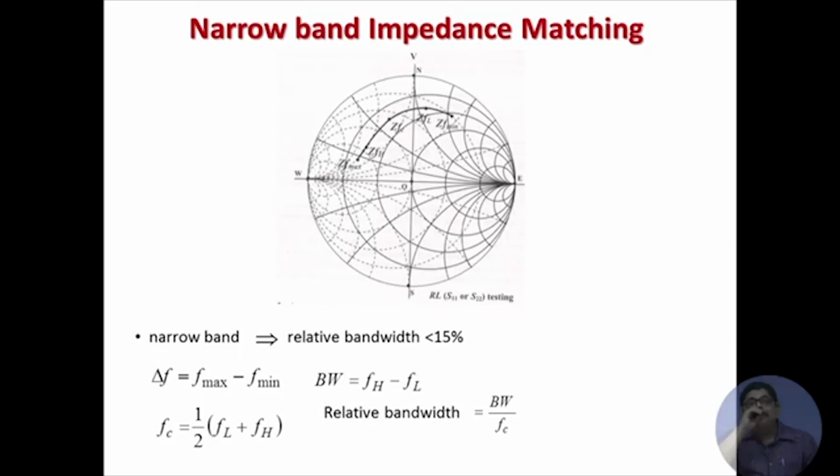So, you see from this diagram that in the Smith chart, if you plot the impedance and even with change in frequency the impedance does not change, it is rock solid at a point, then it is a good impedance match. But as the curve shows, there is generally a variation, a locus, as we vary the frequency. Obviously that variation of impedance should not be much, because then the purpose will be lost, since we are trying to get a particular impedance from this impedance matching network.